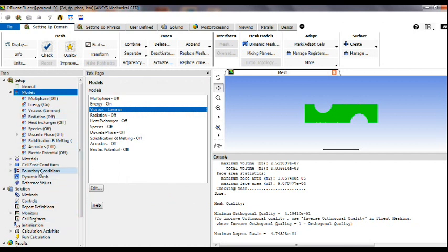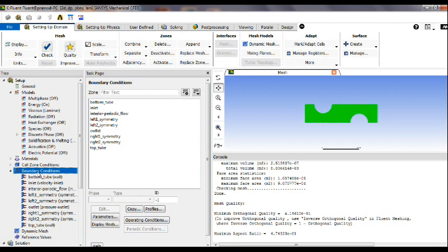And as I said, we have to define the periodic zone. So for that we need an inlet and outlet ID. So here now you can see if I select inlet, it automatically detects velocity inlet, and for outlet it is a pressure outlet, and the ID given is 12 for outlet and inlet is 11. So this ID we need. And after defining the periodic zone, now you can see the change in the type.